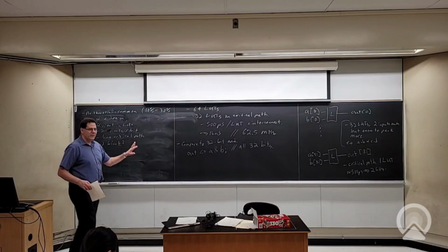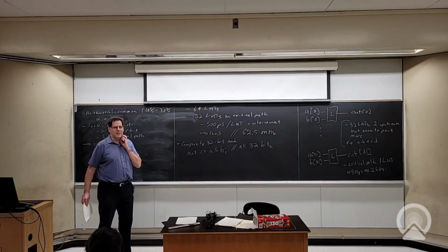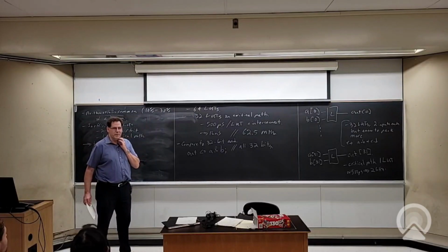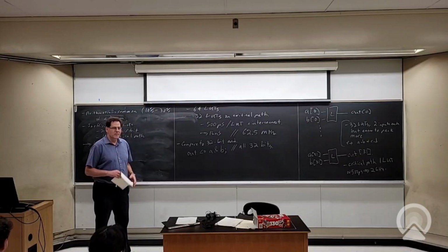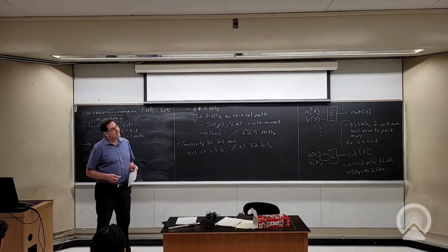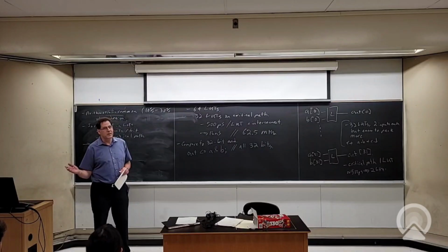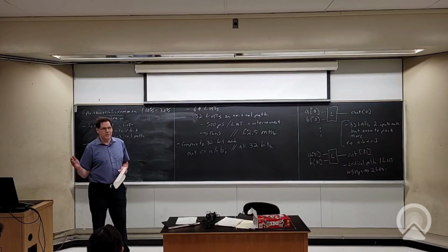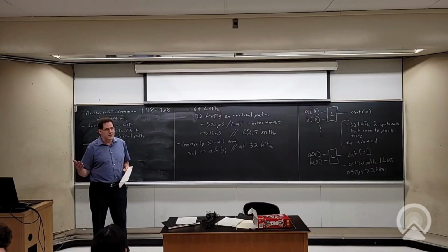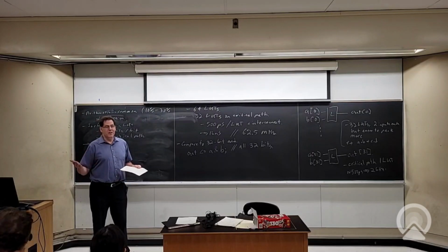Is there anything else I could do about this critical path before we go and harden it? Like, can we just fix this somehow, some other way? Yeah, what do you think? Could you just add a bunch of registers and have the retimer deal with it? Well, you could put registers between all the LUTs. In this case, I'm doing it all with regular LUTs, so I could put registers everywhere. That would solve my critical path problem, although it means I've got a large latency. If I do a 32-bit add, I need 32 cycles of latency, which may be an issue in some design, in a lot of designs actually.